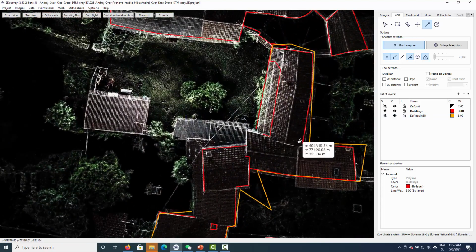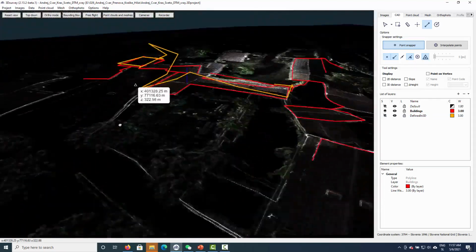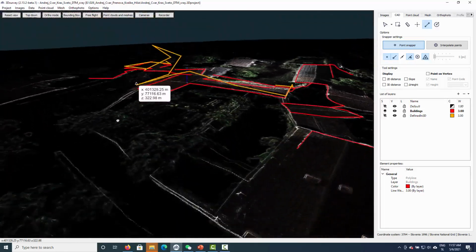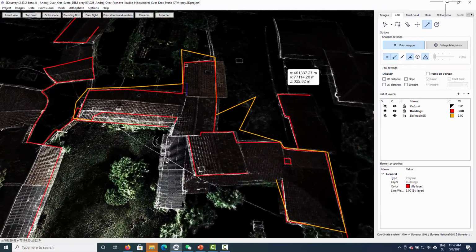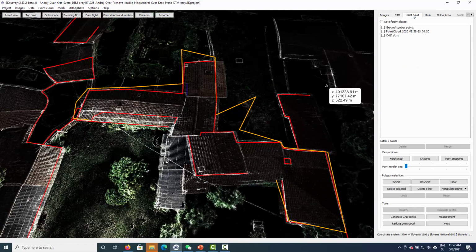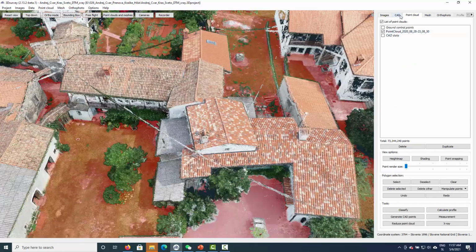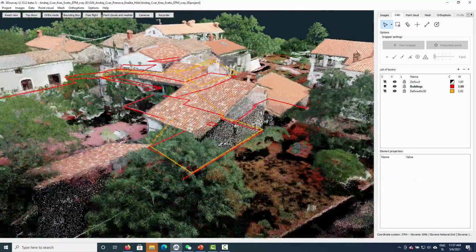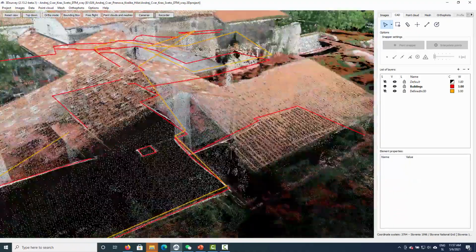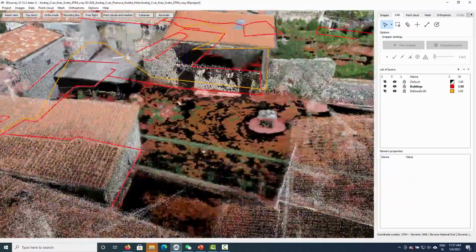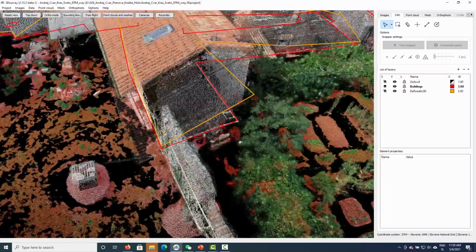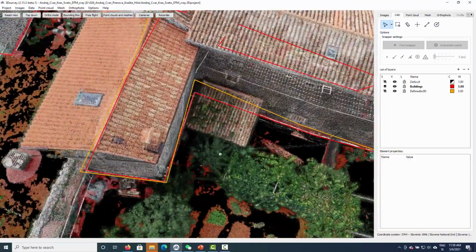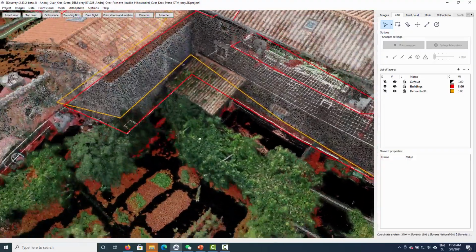Immediately we see one thing. The borders we are drawing now look a lot more reasonable. If we want to check them out well, what we should do is turn on the point cloud, go to CAD now, and see how we were able to define the edges. So here we see that the edges defined like this, we get them pretty well.